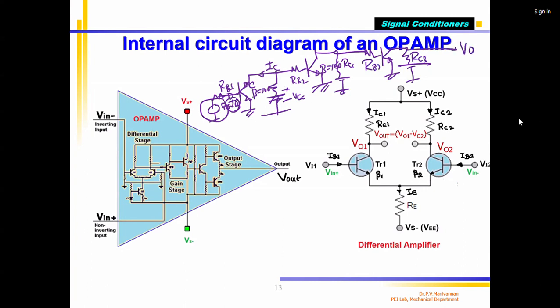Each has a gain of 100. Beta equal to 100. This also has beta equal to 100. Okay. Now I give the input here. I am taking the output after 3-stage amplification using 3 transistors. Correct. This is called a cascaded connection or serial connection.